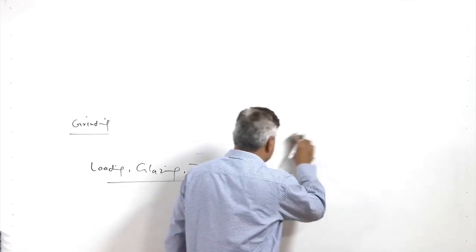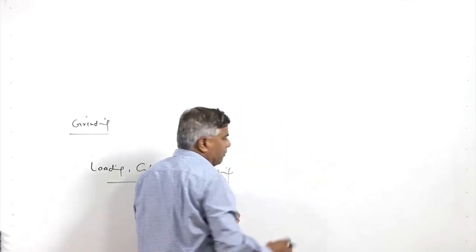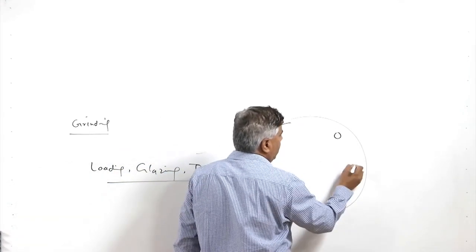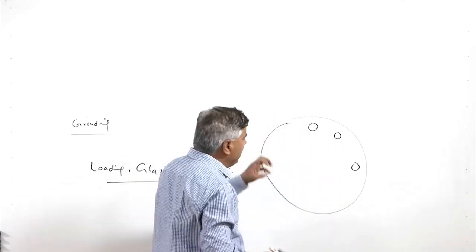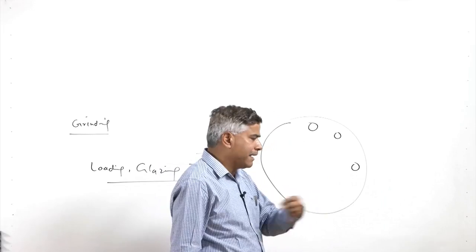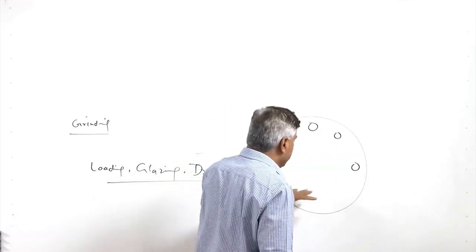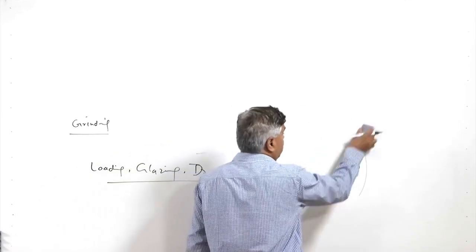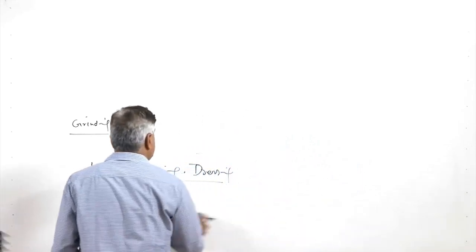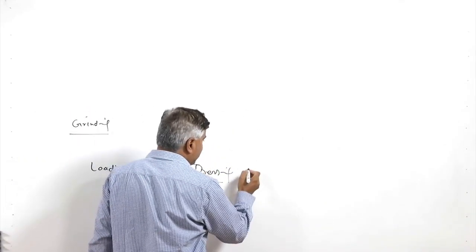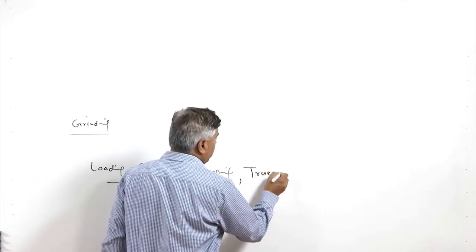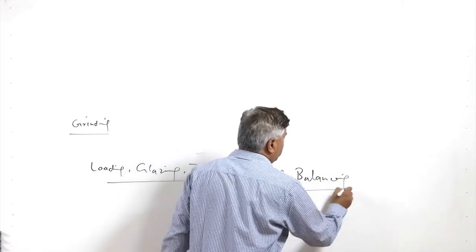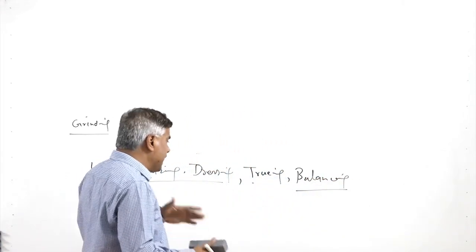the imbalance. So, for this purpose, normally suitable weights are attached to the wheel by drilling holes and filling them with a heavy metal like lead, so that the wheel can be balanced in order to avoid the adverse effects related to the imbalancing of the wheel. So, apart from dressing, truing is another, which is basically for correcting the shape, and balancing is about balancing the wheel in order to deal with the problems related to the imbalance of the wheel.